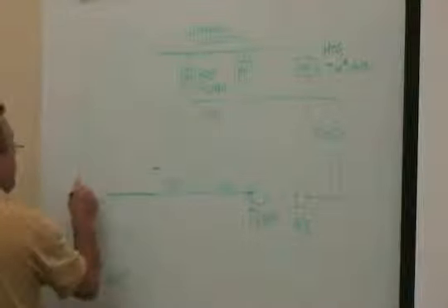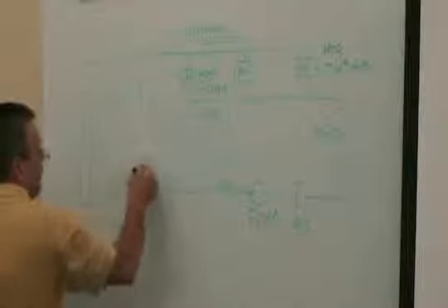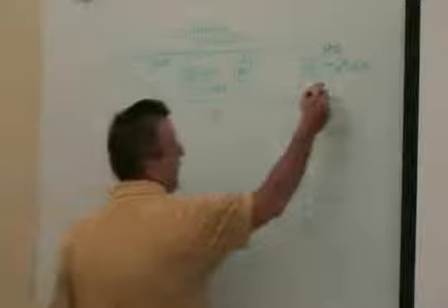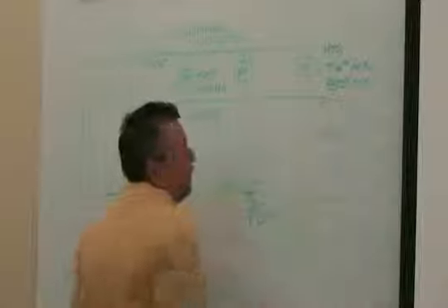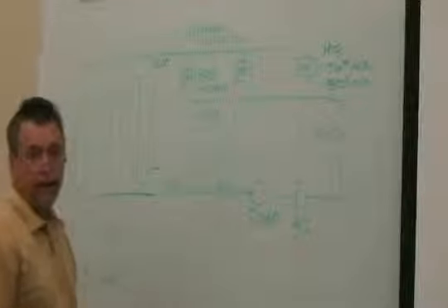So I've got a series of loops in the ground. Some kind of ground loop out here that I might get down to 40 degrees in the wintertime. And with 40 degrees in the wintertime, I'm producing 85-degree air right here. Your skin temperature is about 88 to 90 degrees. Anytime you get below that skin temperature and you blow air on it, it feels cold.